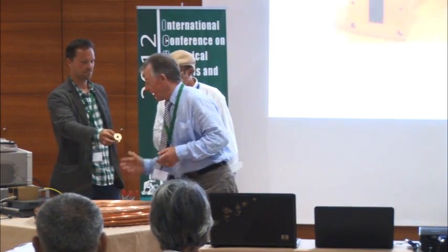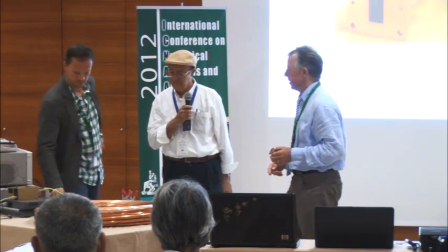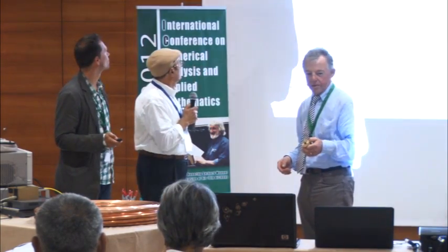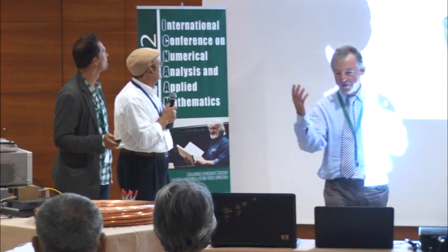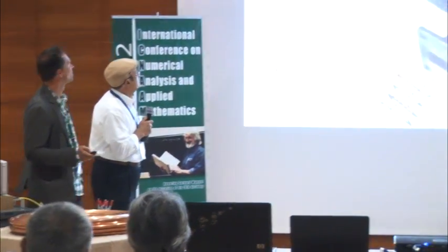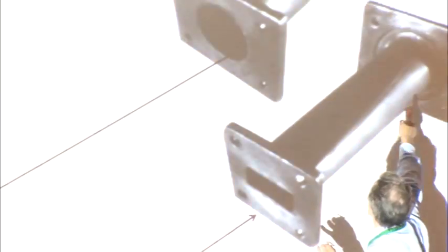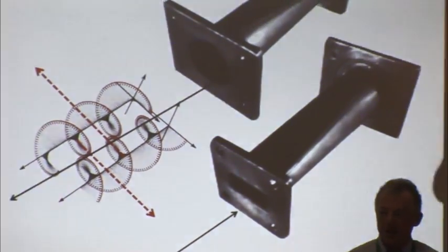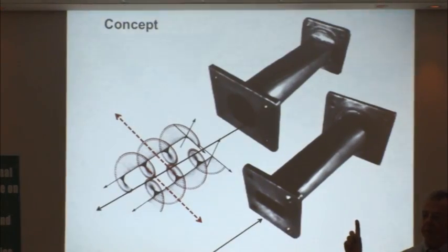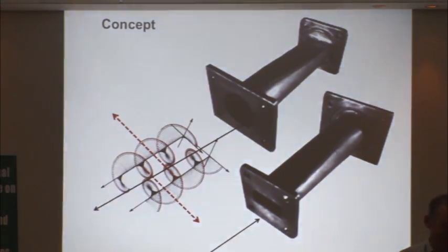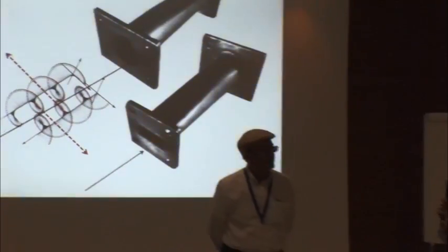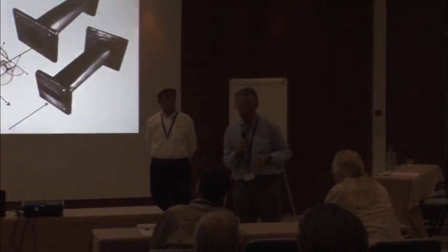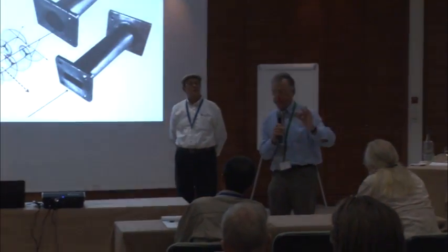We have a special mode in the rectangular waveguide, and here he has shown the picture. Can you show once more the transmission from the rectangular to the circular? This is an important picture from an engineering viewpoint. Here you see the adapter from rectangular to, on the other side, the circular waveguide. And we did this just because it's cheaper. And for the TV people, you can at the same time transmit two polarizations. The polarization is constant. It's connected to the spin of the photon. Therefore, the spin is stable up to the satellite, 40,000 kilometers away from us. So you can see the adapter sends two polarizations. That means you have double the channels.